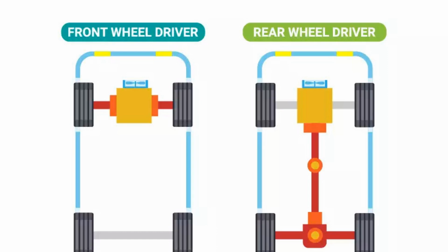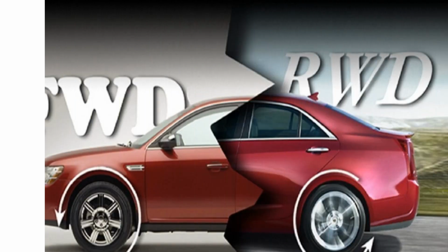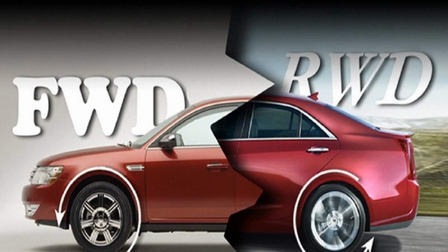On older cars with rear-wheel drive, an uncut beam is used as the rear suspension. In this case, the differential is connected to the wheels by drive shafts through a splined connection. But this type of construction provides a weak level of comfort. Modern rear-wheel drive, as well as all-wheel drive, is equipped with semi-independent or independent suspension. In this type of construction, the joints are mandatory, which increases the cost of production of the car.